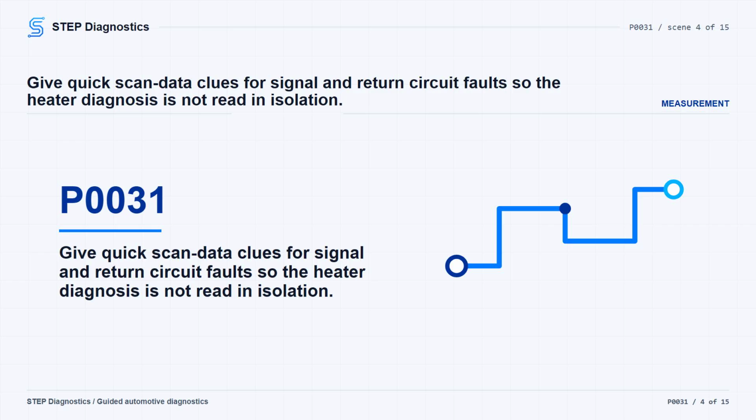With a short to voltage in the sensor return circuits, the affected O2 sensors will read 5.0 volts on the bias signal voltage, and the 0-1 raw voltage reading will be 0 volts because the signal circuit voltage and return circuit voltage are both 5.0 volts. On a cold engine start under that type of condition, the 0-1 raw voltage reading will start at 2.5 volts and decrease to 0 volts as the sensor warms up.